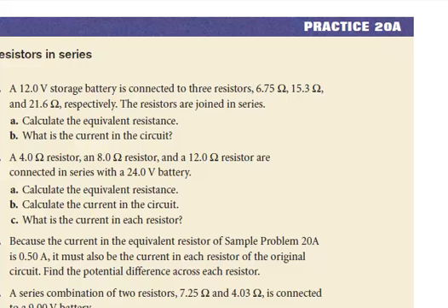Everything is on or everything is off. A break in a circuit anywhere, the entire circuit is going to go out. Adding more resistors increases the overall resistance, decreases current. Current through each resistor is the same. Potential difference is not the same. It's based on the size of the resistor.